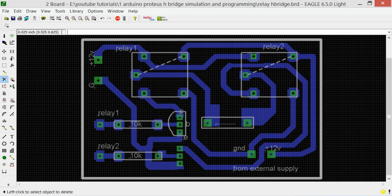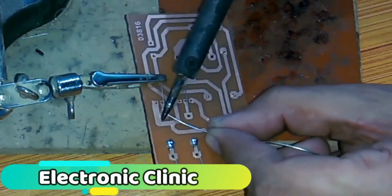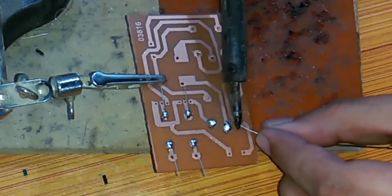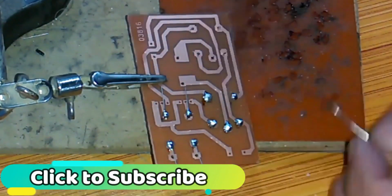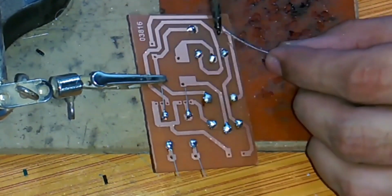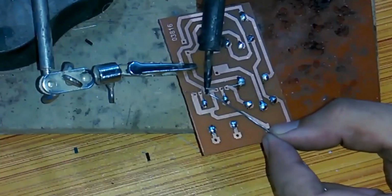Now let's use the same components, two 2N2222 NPN transistors, 10K resistors and relays to make an H-bridge module. So this is the H-bridge. These are two relays and two 10K resistors, and now we will do the soldering. So first of all we will solder the 10K resistors, and then after that the two relays. So now these are two transistors.